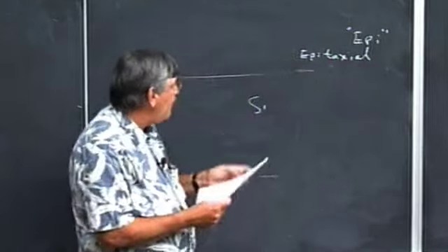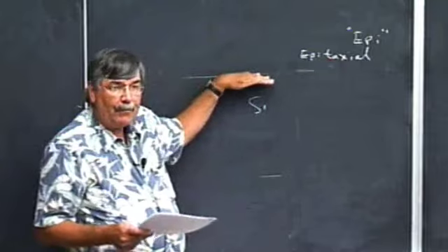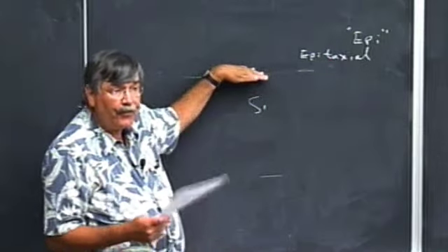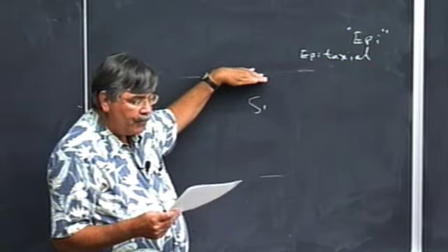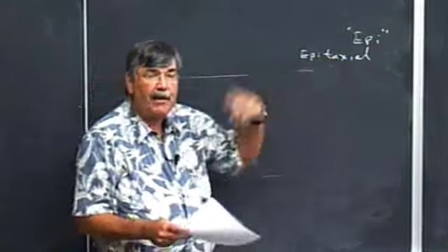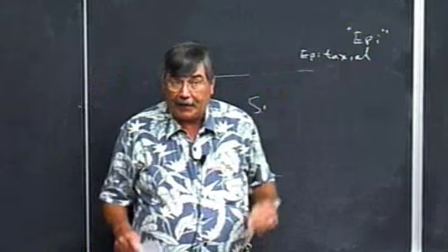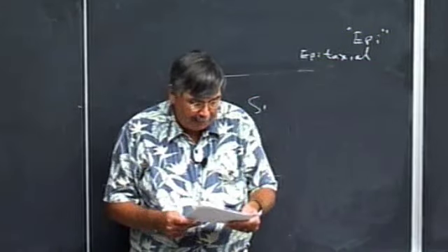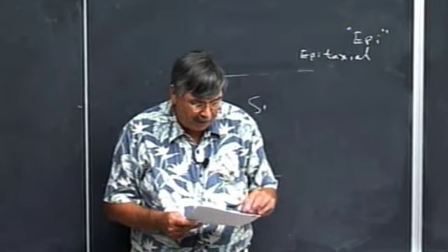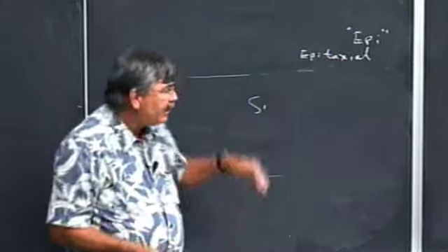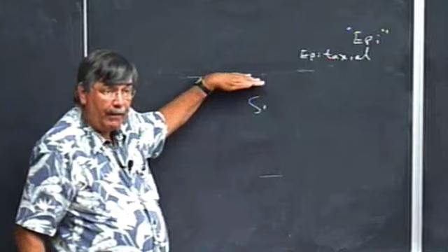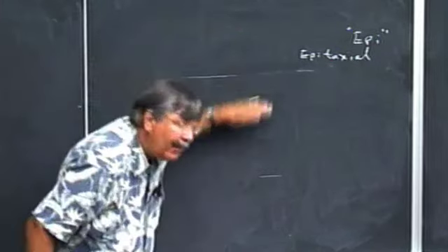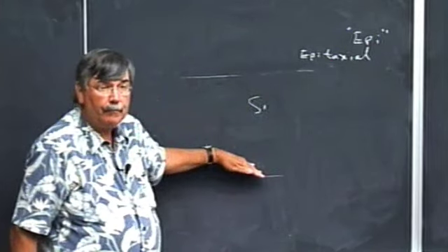The alternative might be that you can deposit various impurities in liquid, crystal, or gaseous form, or you can have diffusion from one layer into the other. That's actually 4 different things. But ion implantation is the number one way, and diffusion after that. So a lot of times you'll implant or get a certain controlled dose at one place in the device and then diffuse it down. That's very common.